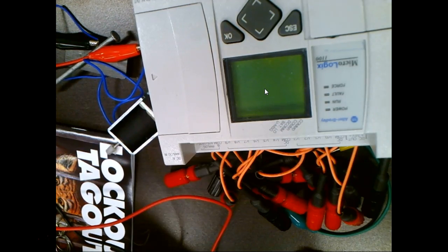What's nice about relays is I can use DC to control AC. The coil might be a DC coil running on 26 volts, but I might be controlling 6,000 volts on my contacts. But the big problem we have with relays is they're not what? Fast. We can't use them in applications that require extremely high speed.